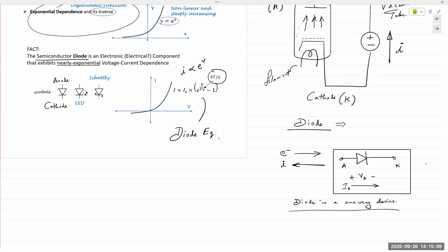If you apply AC to them, they're going to get blown out. So the adapter's job is to convert AC into DC. At the front end of every power supply, every adapter, every mobile charger, at the front end of every single one of those is a diode circuit. And the diode rectifies or converts that AC into DC.